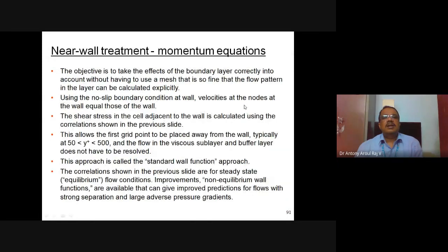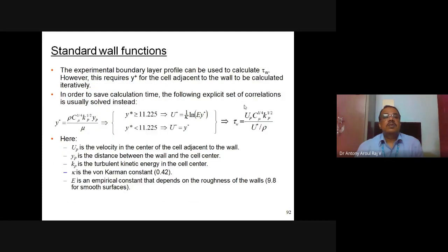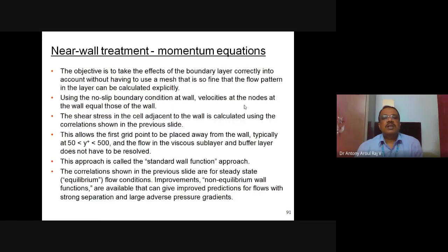Near-wall treatment: how will we be giving boundary conditions near the wall for the turbulent solver? Two methods are there. One is the standard wall function approach. Another one is the two zonal approach. So now we have seen that.